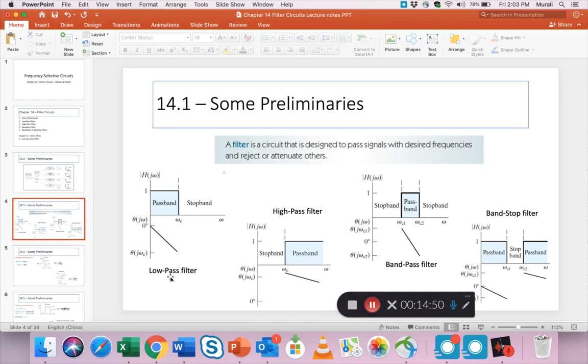Similarly, you see the phase angle drawing below. Now both these drawings in this chapter, for some reason the writer has chosen not to use Bode plots but just regular plots. So the magnitude is not in dB, not in decibels, but just a ratio. And he uses Bode plots in the next chapter for active filters. But for now, you still get the point, which is that there is magnitude and there is phase angle, right? Both are necessary to talk about frequency response. And so the phase angle is the one on the bottom, and you can see that the phase angle also steadily drops from 0 degrees to minus 90 in this case, generally, when you are approaching omega c, the corner frequency. Okay, and similarly you can track the other three and try to understand.